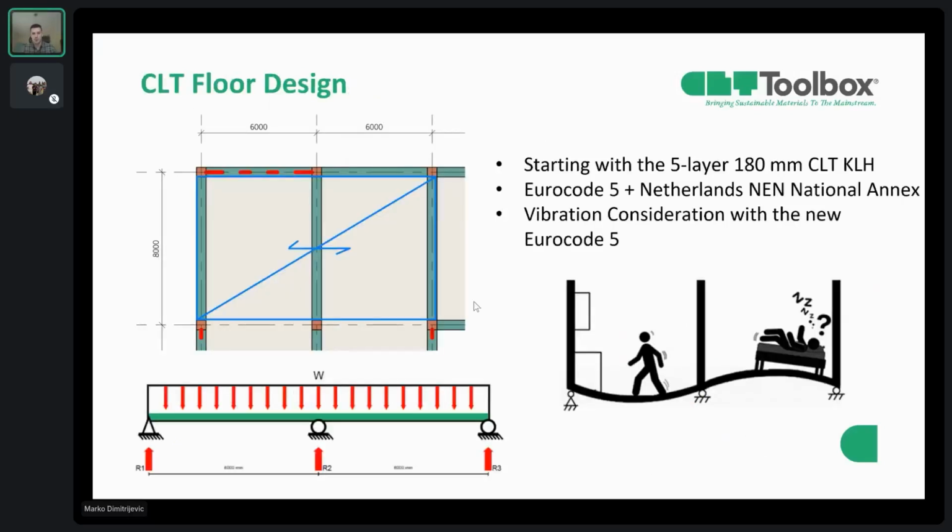Let's start with the floor design. So we'll check 5 layers, 180 millimeter CLT made from KLH. We will also use Eurocode 5 plus Netherlands National Annex. And we'll spend a few minutes on consideration of vibration analysis, to see how different analysis impacts our design and what the options are in our tool.